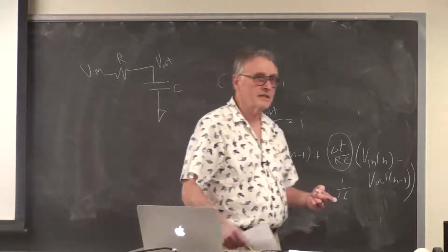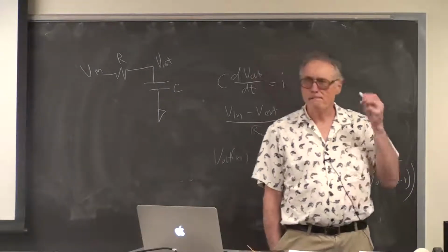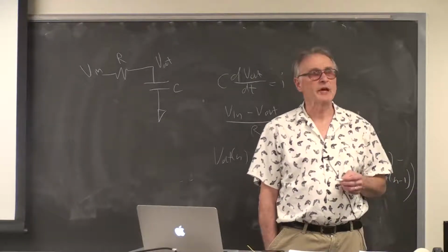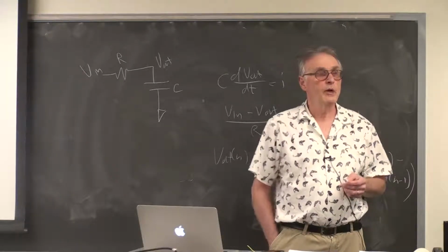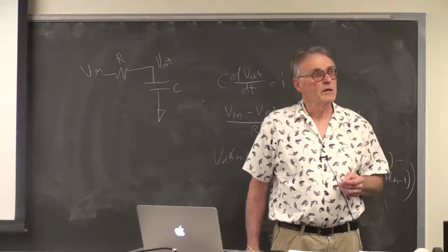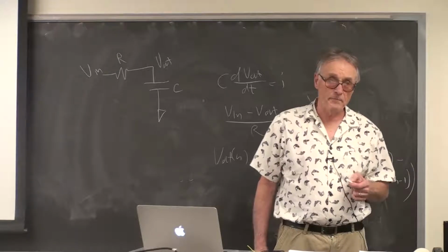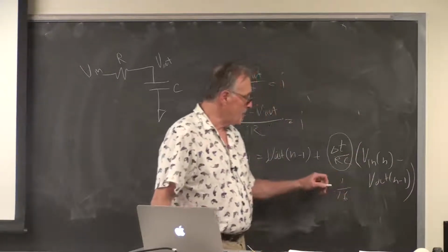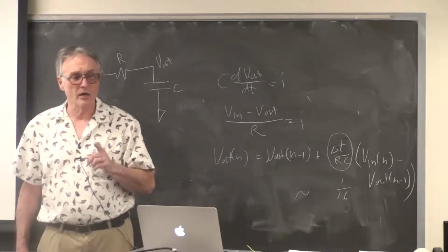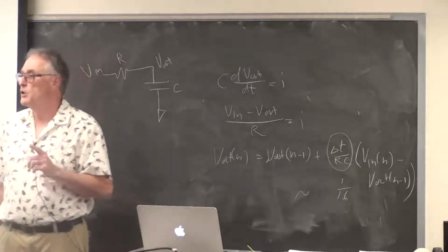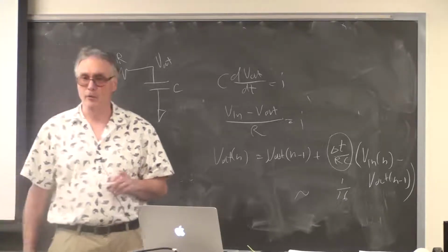Why did I choose 16 sample times? So 16 sample times is like 0.016 seconds. That's still pretty fast with regard to any of the dynamics of the system. But averaging over 16 samples is enough to reduce a lot of the PWM noise from the calculation. So you might want to experiment with this.